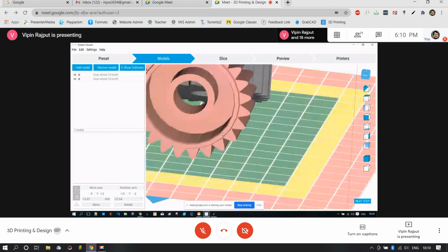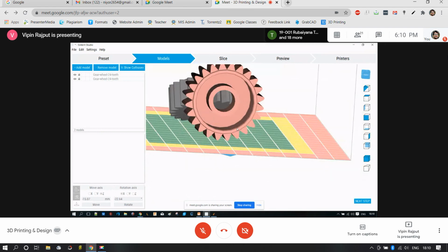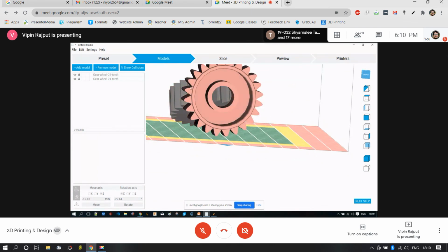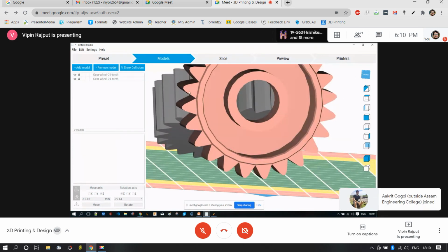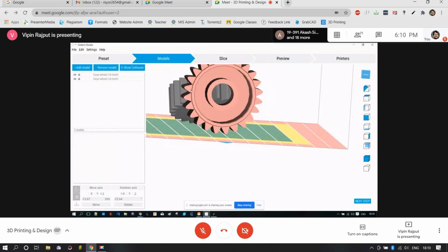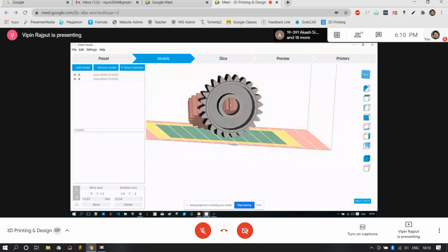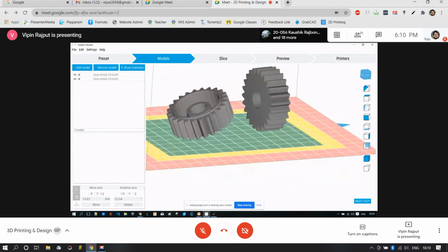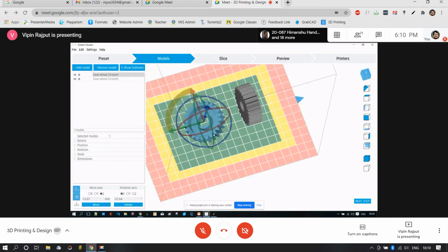Let's say the model was printed successfully. In that case too, when you remove the excess powder and the excess material around the model, you could experience that these teeth may not be as per the dimensions. Let's say the angle was 50 degrees, you might experience some contraction or expansion in this particular hinge. Simultaneously, the cylindrical region may not be as cylindrical as it is in the software, so you might experience some kind of aberrations. That's why it's always advised to use the particular orientation.